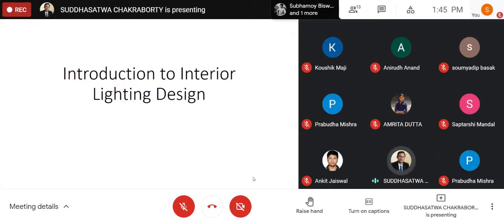That definitely depends on the different conditions. Just for an example, if I have a completely interior place, the design approach will be something different. If you recall our previous classes, when we were talking about the coefficient of utilization or utilization factor, we mentioned that there is a very clear demarcation between the different types of lighting design. The most fundamental is that for indoor cases, we are getting support from the walls, from the ceiling, from all the surfaces other than the floor.